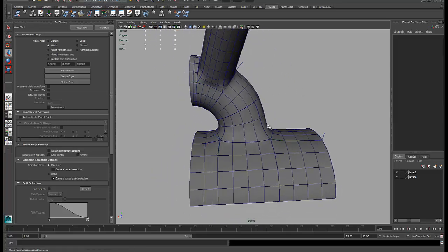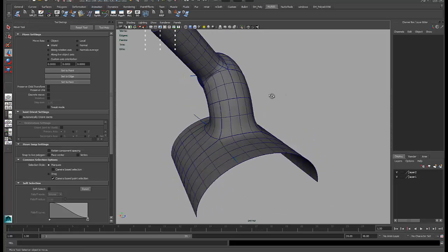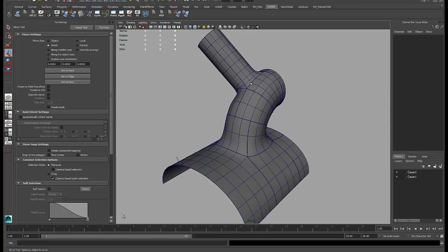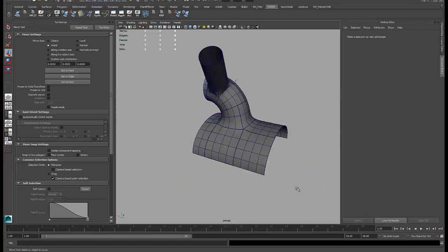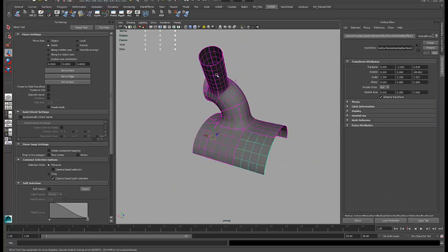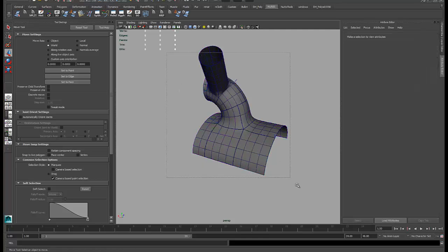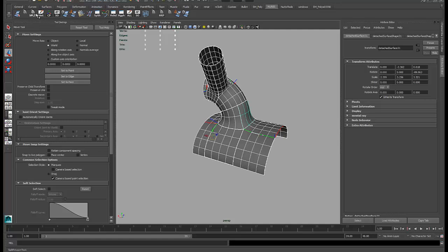Now it's up to you whether or not you want to just attach these like I did with the lower ones, or put a loft in there like I did with the upper one. Remember, every time you attach or detach or put a loft in there, it's really just a temporary measure, and what you're doing is just nudging these closer together so that the global stitch has a better chance to work. So my final step here, I still have a lot of construction history from the last global stitch. So I'll select all my surfaces and delete the construction history.